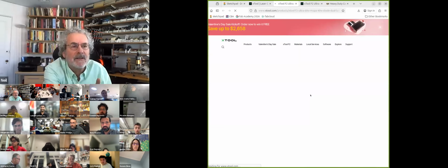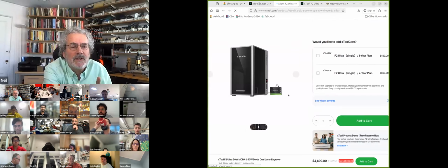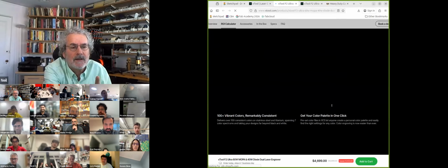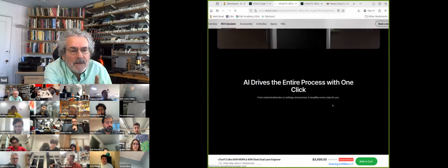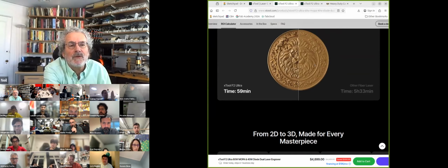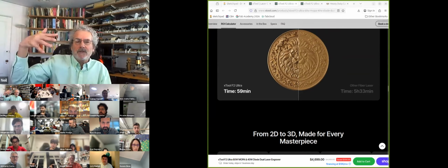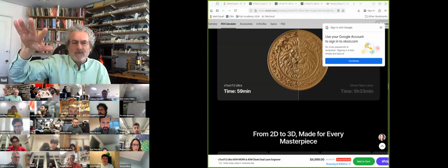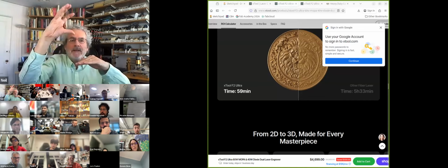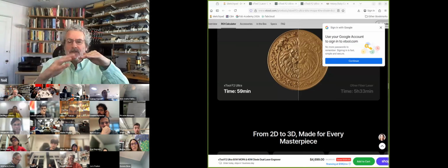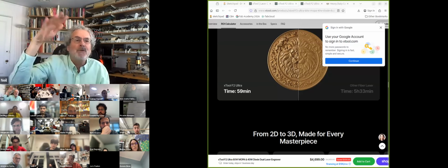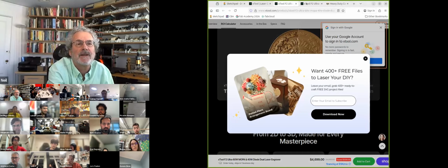We're going over time, but I'll take just a minute and then we'll wrap up. When you do deep embossing, let's see, this is taking too long. Okay, sorry, this is what I wanted to get to. When you start to do this sort of embossing, it has a vision system to match the surface if it's not flat. And then as it does the laser cutting, the whole head is moving up and down to move the focus as it moves through that. So you don't need to do that for thinner cutting and flat stock. You need to account for that for deeper cutting.